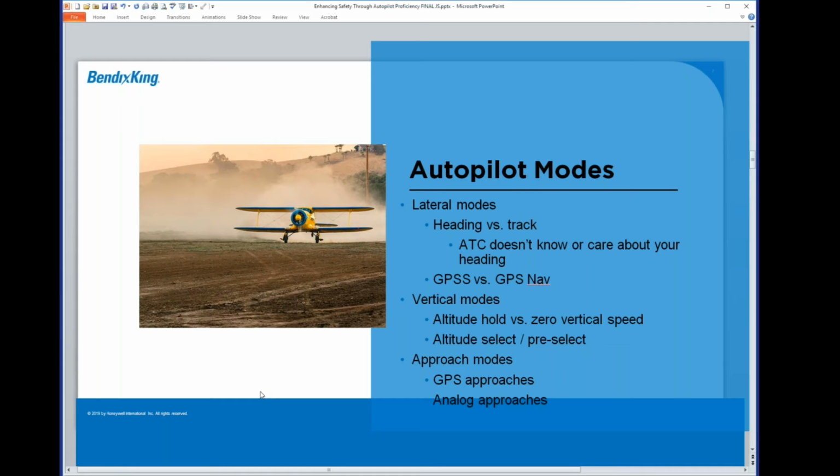Because when you think about air traffic control and the instructions that they give you, ATC has no real idea what the heading of your aircraft is. They can infer it, but what they're really going to do is look at your track across their screen and give you correcting instructions. So if they tell you to go to heading 090, you put it on 090, but the reality is you're tracking 080 because of a crosswind. Well, as an air traffic controller, they have to keep that in their head and now issue you 10 more degrees because they know where you actually should go. And exactly, I got a little comment from someone, give me 5 more to the left. Exactly the way that you get.